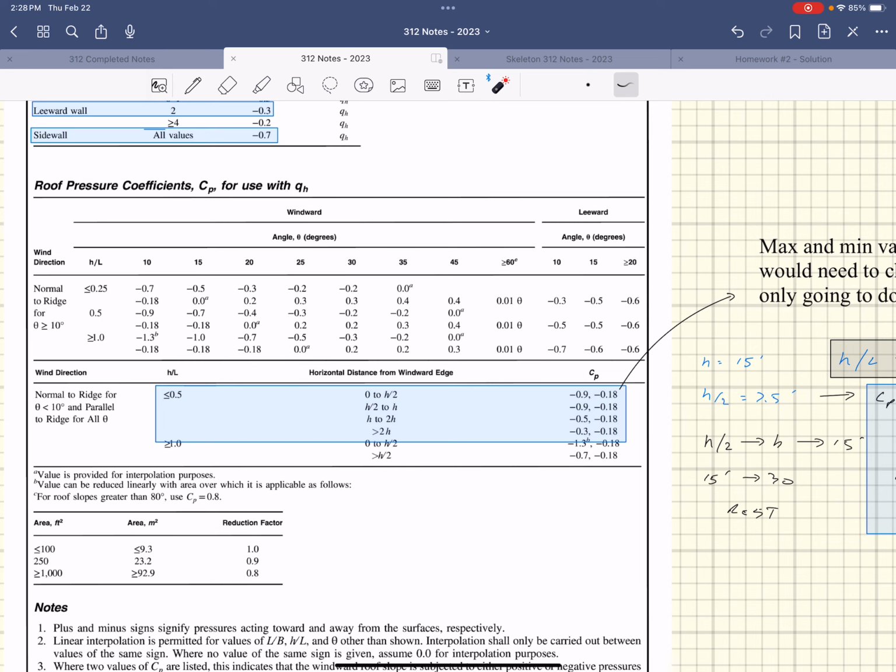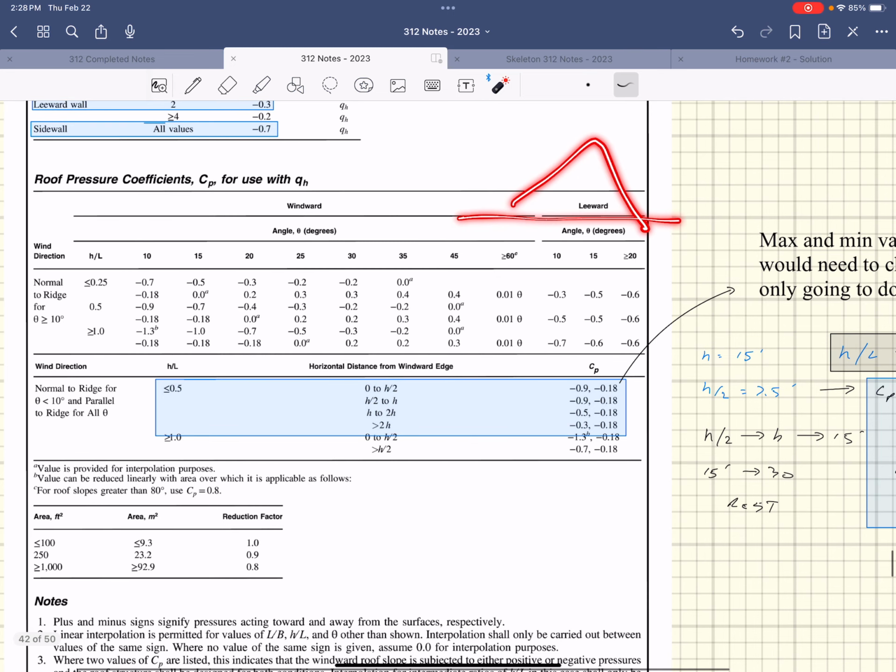It's kind of hard to think about, like if you're designing a rafter, that having that uplift from the wind actually helps you, because if you had some sort of truss that was carrying loads, and you have your snow loads, for instance, acting down like this, and then you have these wind loads that are acting up like that, actually having more upward wind forces would actually help you in your design.